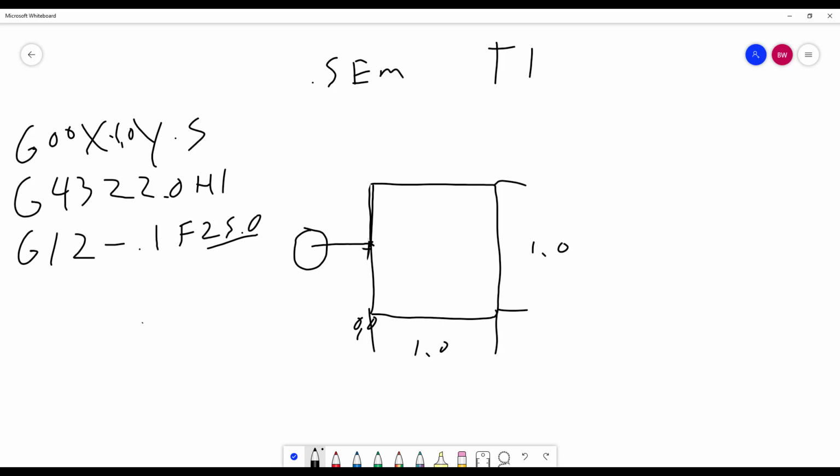The lead in has to do with the amount you're trying to compensate, which in our case is 1/4 of an inch. That's the radial compensation. You do type in ½ inch in the controller, but we're compensating 1/4 of an inch, which means we need to at least lead in 1/4 of an inch. I try to do at least a diameter, because if you lead in just that 1/4 inch, for comping it to size, you run into issues.